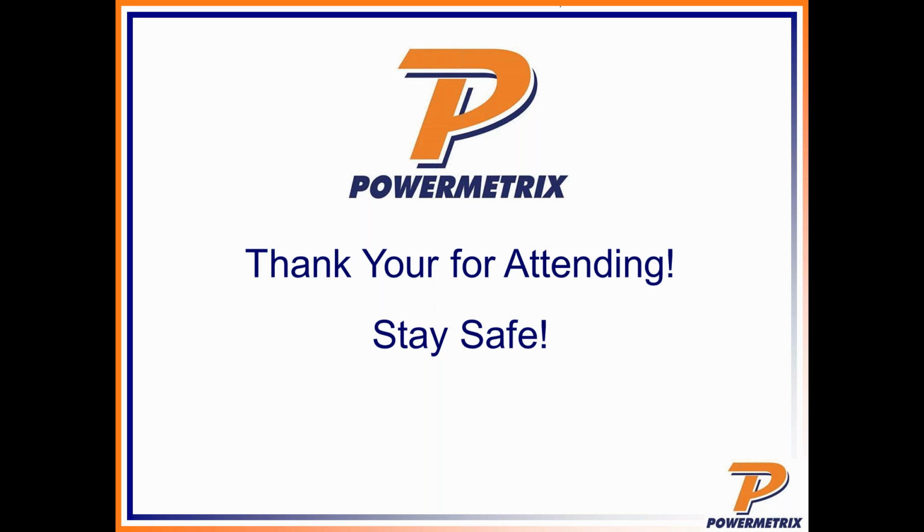Looks like some questions about how much burden you should add. Generally, if I'm out on site and I see a burden on a CT that may be rated at 0.5 ohms, I generally have people put the max burden that they add as either 0.5 or 1 ohm. Just enough so that you know you're going to send that CT into a situation that is above its burden rating, just to see how it performs if something bad were to happen. And that's kind of what I do.